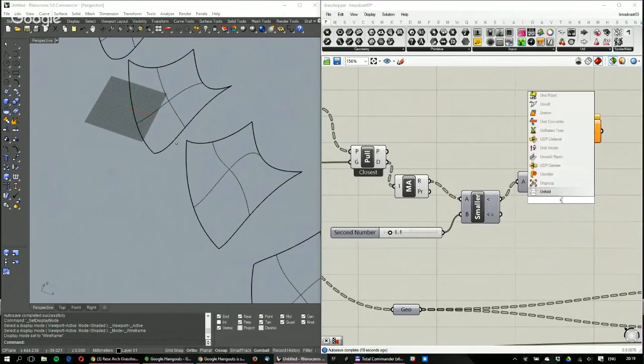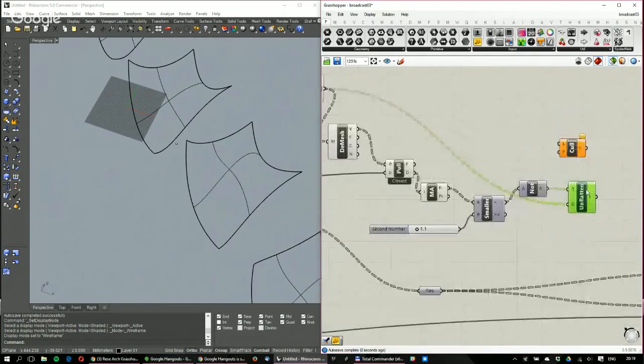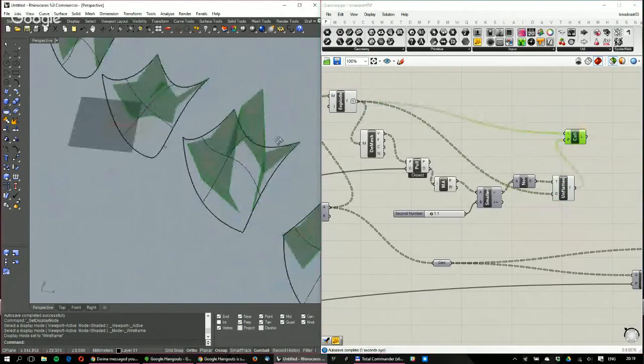Or I can unflatten this data tree, and if they have the same amount of elements, it simply sorts it into the same fashion. So there are 61 values here, but they are sorted differently. And now they're sorted perfectly like the faces exploded here. I will call those faces that are touching. And yes, it looks like it removed the proper ones.